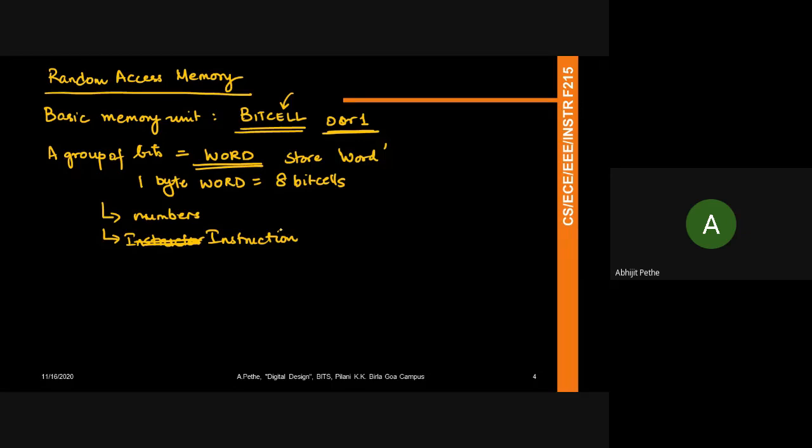Many times, if you want to perform say 5 or 6 processes one after the other, you can load them up in a memory, and then the memory can pop out instructions one at a time, and that particular instruction gets executed, and then the next instruction. Along with the instructions in memory, you'll have a program counter. The program counter will keep pointing, in computer science parlance, to the next word in the memory, which corresponds to the next instruction.